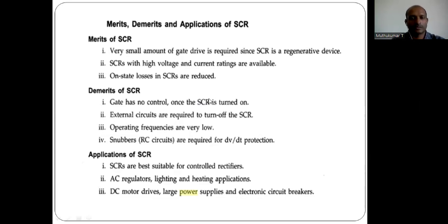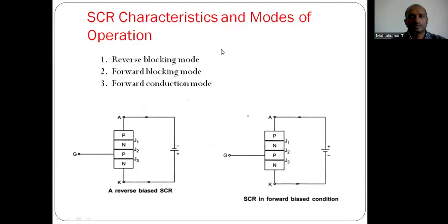Applications. Generally, SCRs are used as silicon controlled rectifiers, that is, controlled rectifiers that control the output voltage with the help of the gate signal, AC voltage regulators, lighting and heating applications, DC motor drives, large power supplies, and electronic circuit breakers. These are the applications.